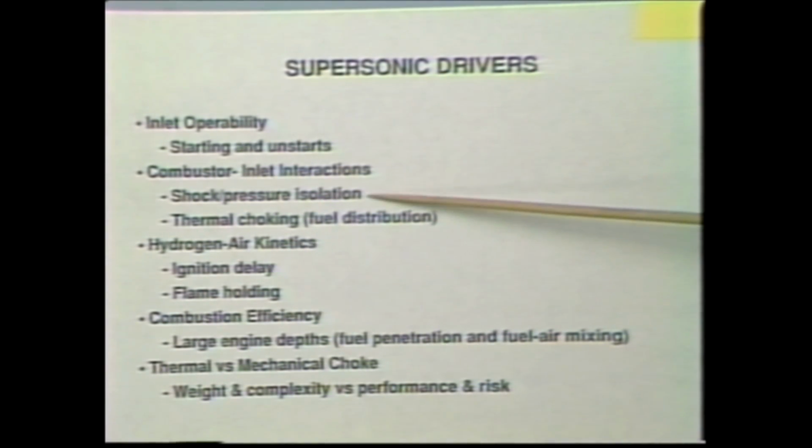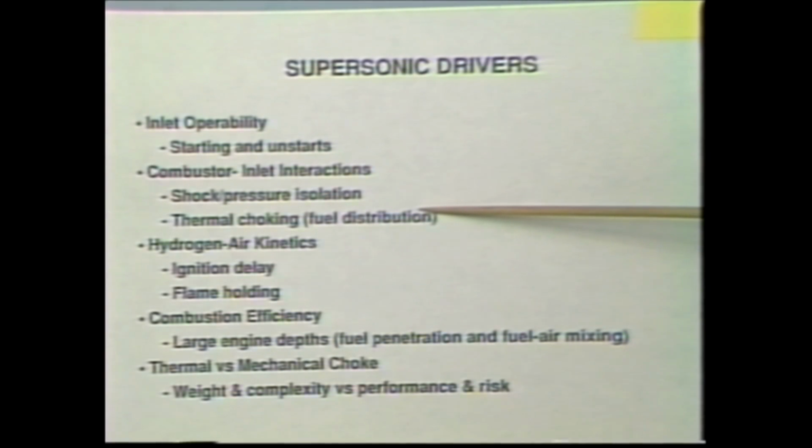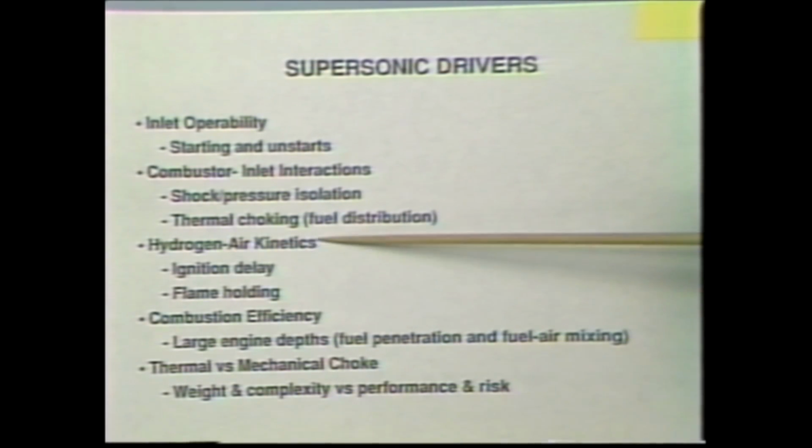If you're not careful, that can cause interactions to feed upstream, boundary layer separation or whatever mechanism to feed pressure upstream, and you don't want to feed high pressure upstream on your inlet ramps, because that's aft facing area and that's drag. Thermal choking is an issue, adding so much heat to the flow that it hits Mach 1 before you've added all the heat.